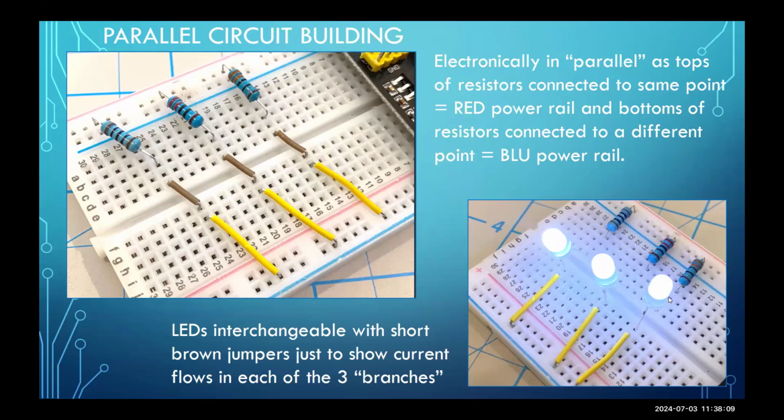This is likely to happen for several reasons. First reason, the LED might be backwards. Remember, the LED is polarized. So if the LED is backwards, you've got to find that LED, the one that's not lit, pull it out, flip it around, and stick it back in the circuit. And hopefully, if that was the singular cause for the LED not lighting, then presumably the LED will light.